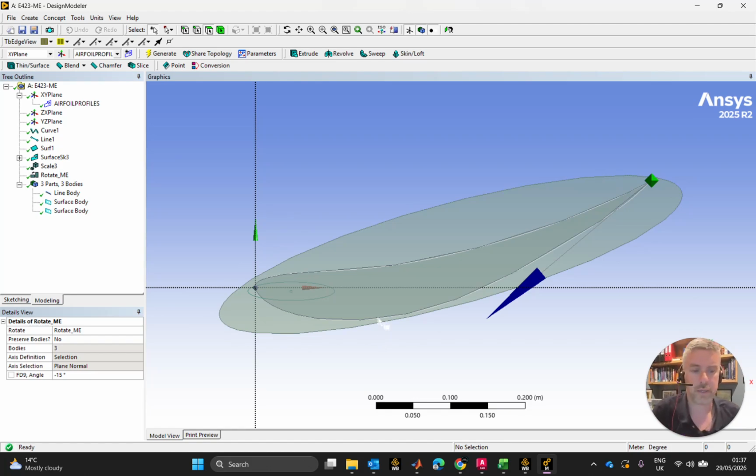So that's hugely important, because that means all the meshing elements here that are local and pushed up against the airfoil wall will not change. There will be areas out along here that'll change, but that's fine. The physics there is just not as intense.